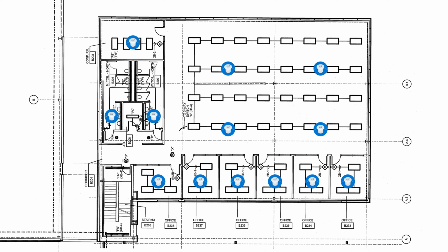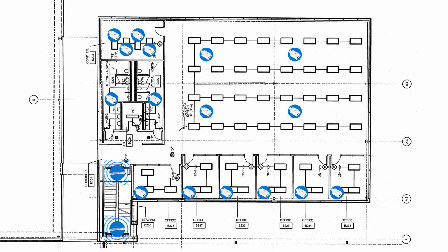The Amatis system has 2 types of fixture controls: smart drivers and advanced load controllers. Smart drivers are most commonly used in fixtures where you're retrofitting a fluorescent tube and ballast to LED. In this example, we've placed 2 smart drivers in the stairway. Advanced load controllers are used in all other instances for controlling individual fixtures up to complete circuits.